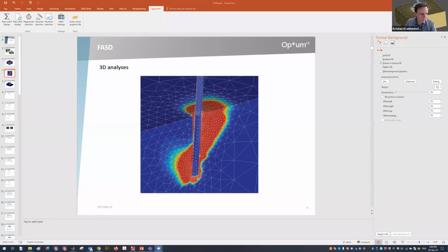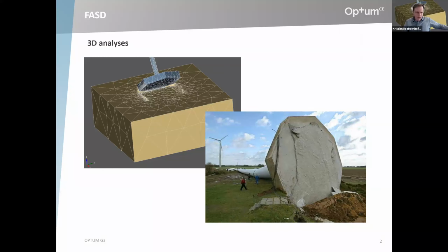There weren't really very many slides to do with the initial words there. What I wanted to show was some typical 3D problems where you are faced with this question of what friction angle you should pick, the one representative of biaxial, say plane strain, or some other friction angle representative of other stress states.